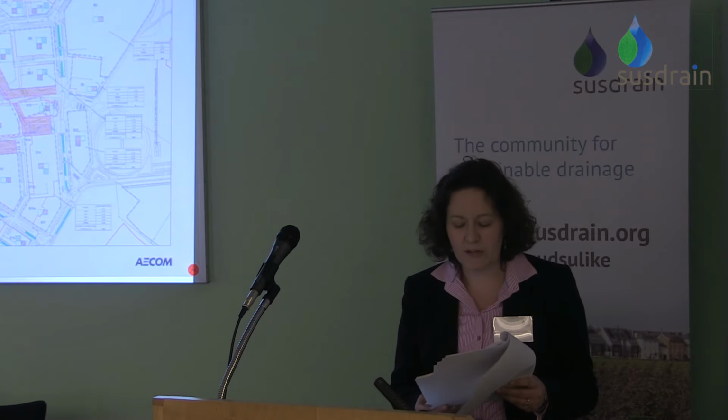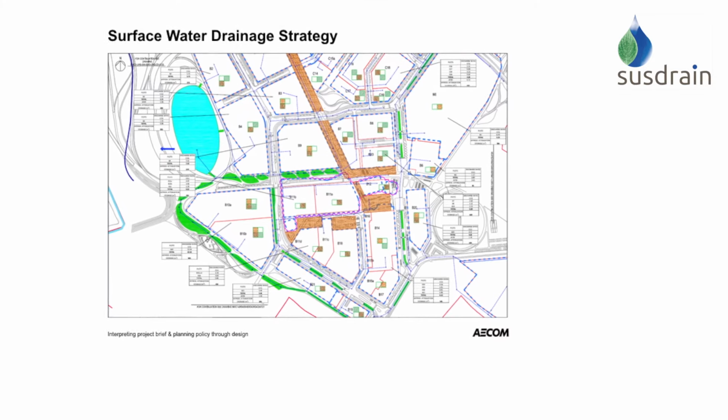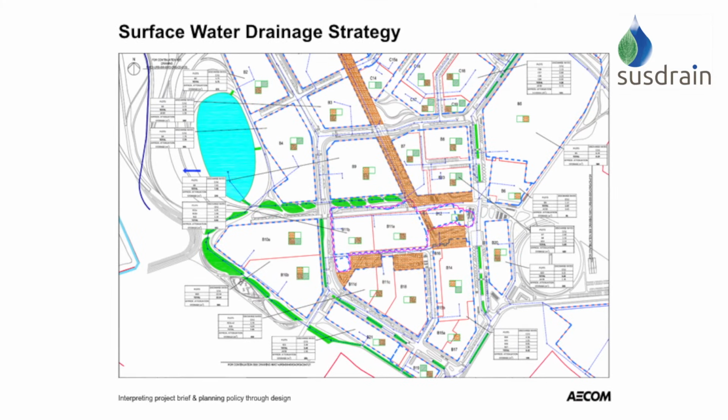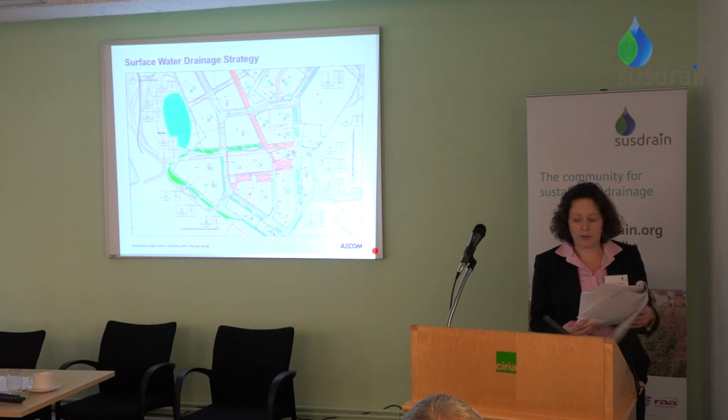Runoff from the impermeable areas was assigned to the drainage networks in order to determine the size of the swales and subsurface pipe and manhole network. The strategy identified the likely attenuation volumes required on each plot based on an assumed percentage impermeable, and which forms of attenuation we considered were likely to be suitable. The strategy also identified the volume of attenuation and long-term storage required in each of the lagoons. This document referred back to the flood risk assessment, but also set the framework for the RMA designs that later followed.